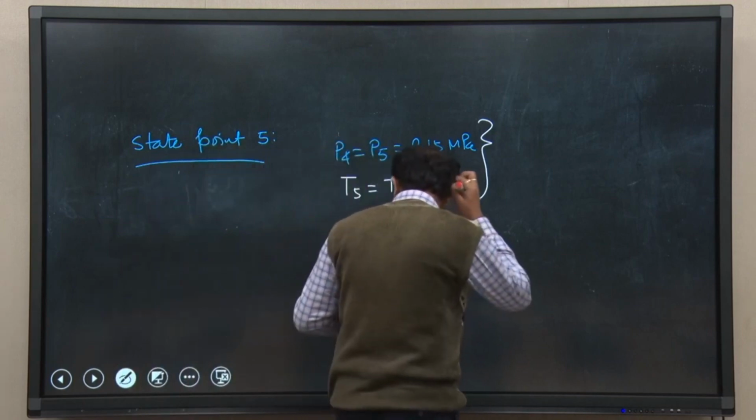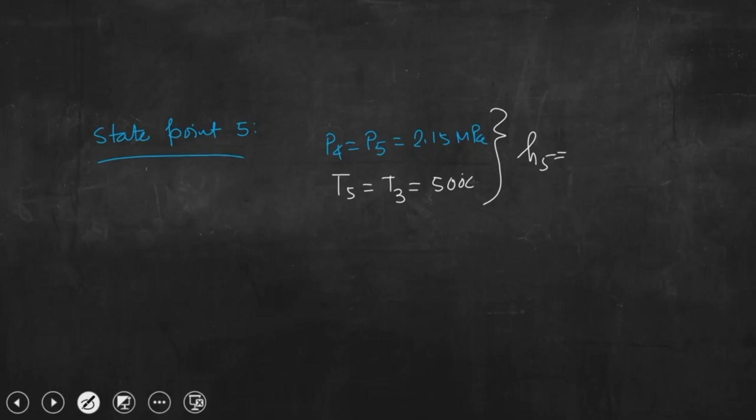So, basically at P5, H5 is 3466.61 kilojoule per kg. So, we can find out Tg at that pressure, and knowing Tg, if Tg is less than T5, then definitely point 5 will be in the superheated region, and we can go to the superheated table to calculate H5. So, ideally we also have calculated H5.